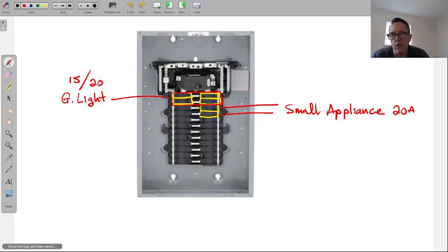So we never want to overload past the breaker's ratings for those reasons. Especially, you trip a 20 amp breaker, not a big deal. You start tripping a 150, you're standing in front of it, turning it on, or the homeowner is. This can get dangerous. There's where melting can happen, and sparking, and I'm not saying explosions are that dangerous, but it is just a bad situation to trip a main breaker. Your panels and stuff, they'll have a higher tendency to melt probably, right, and not trip. The older ones? Yeah. Yeah, absolutely.